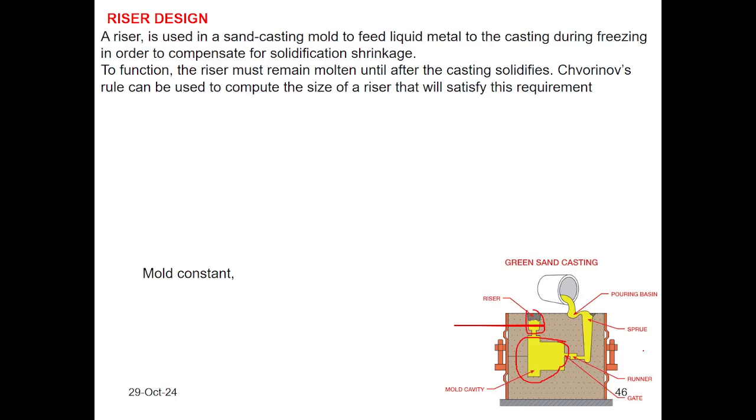To keep the metal in liquid phase within the riser, design the riser such that its solidification time is greater than the solidification time of the material within the cavity. Numerically, to determine the solidification time, we use Chvorinov's rule.